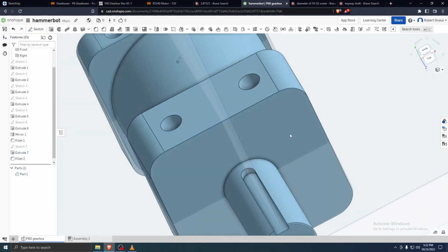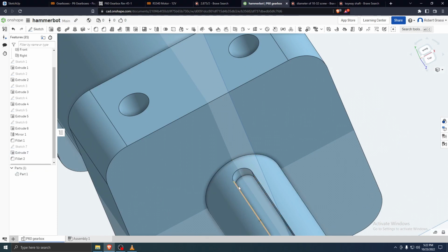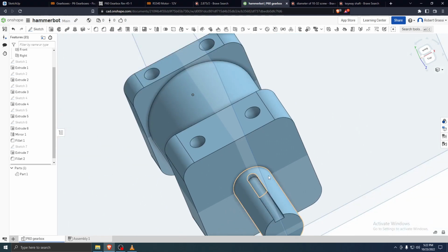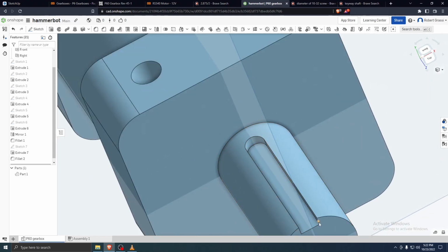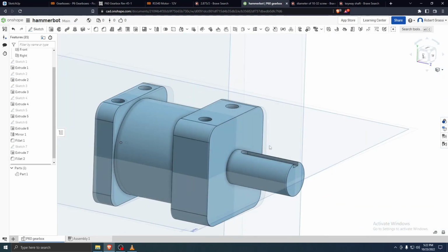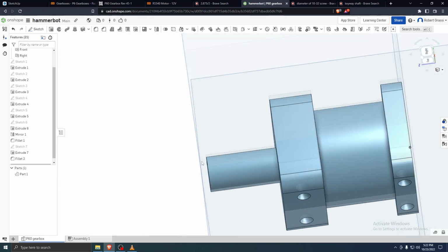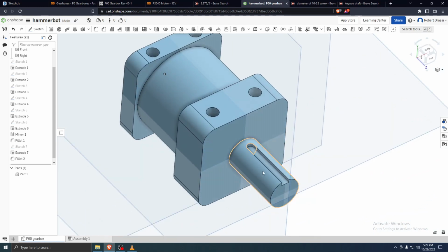And the reason why there's a lot of curves in geometry and stuff like that in general when you're building stuff is because if you think about the way that certain things are machined or made, a lot of the times they're using a circular end mill or a circular drill bit, right? So having the sharp corners is not always possible. So that's why learning to use fillets is important.